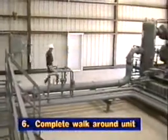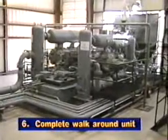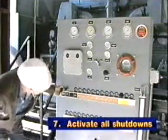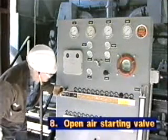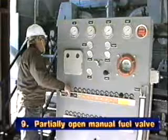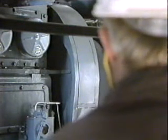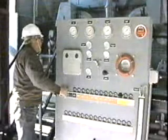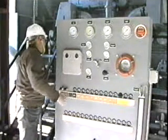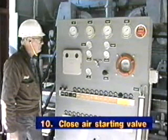Do a complete walk around of the unit to be sure the area is clear of all personnel. Now activate all shutdowns on the control panel and open the air starting valve. Then partially open the manual fuel valve. This will start the engine as the fuel is ignited by the spark plugs. If the engine does not catch within 5 seconds, repeat the cycle. When the engine does fire, close the air starting valve.